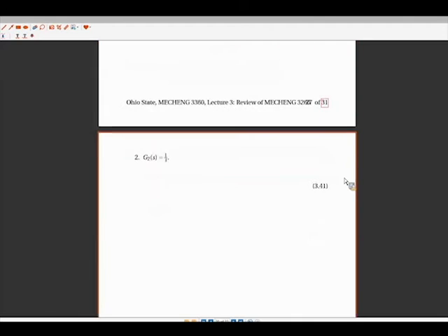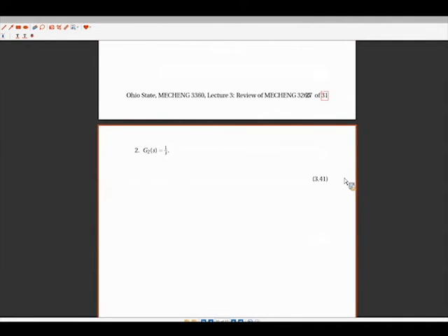All right. Next component is 1 over s. The standard substitution that we do is turn this into 1 over i omega. And if I want to get this in a little easier form to work with, I multiply top and bottom by i. That equals negative 1 over omega i. If I want to plot this in the complex plane, the complex number negative 1 over omega i is due south. It's along the negative imaginary axis. Say, for instance, it's this point.